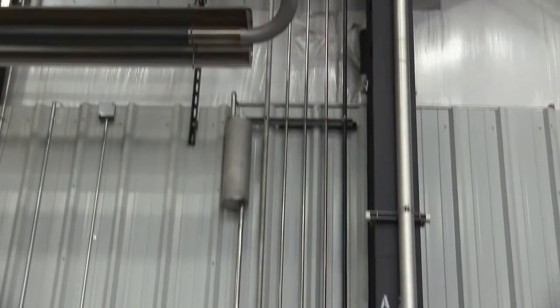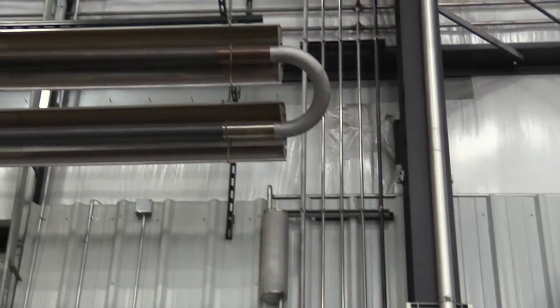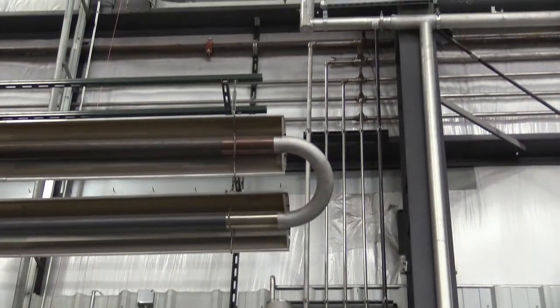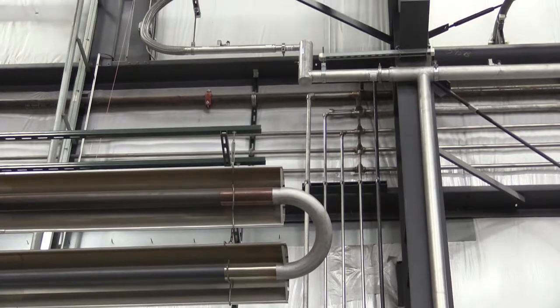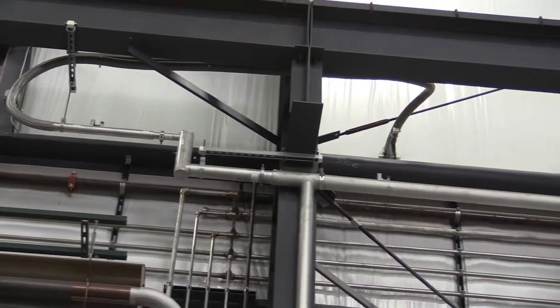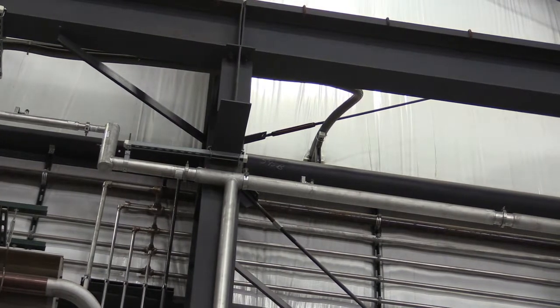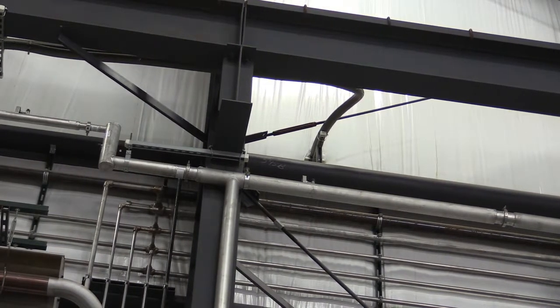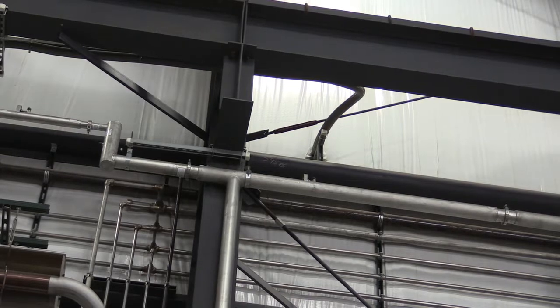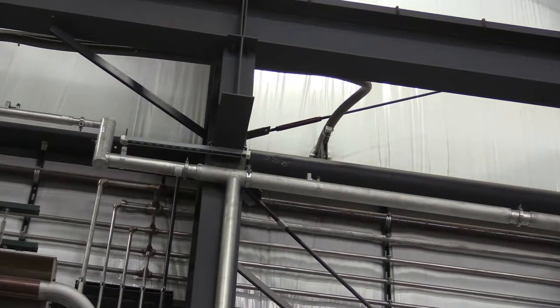Multiple types of cryo vent configurations are available. The standard cryo vent has a non-insulated exhaust and will create a frost area at the exhaust. This must be considered when designing the system. Cryo vents with a bayonet exhaust will allow use without frost. Two means exist for the exhaust of this type of cryo vent.